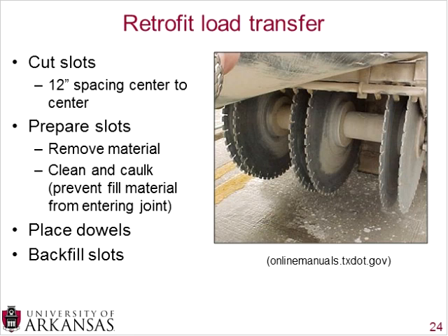You then want to caulk the areas. Because these are being put at joints, you want to make sure that no fill material enters that joint, and that's what the caulking does. After doing that, you simply place the dowels and then you backfill your slots.